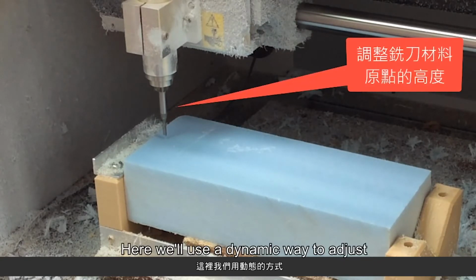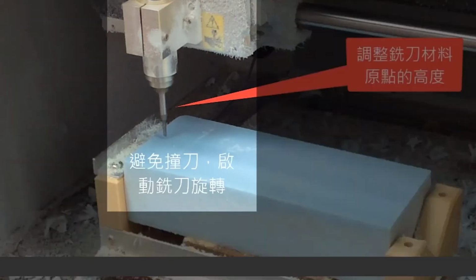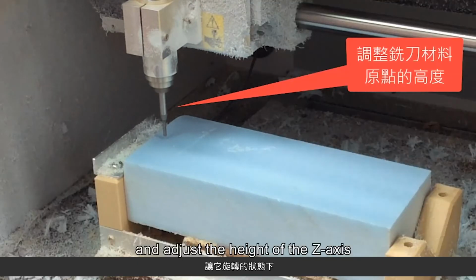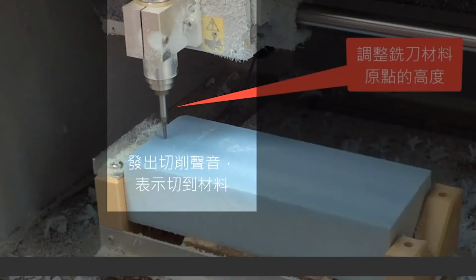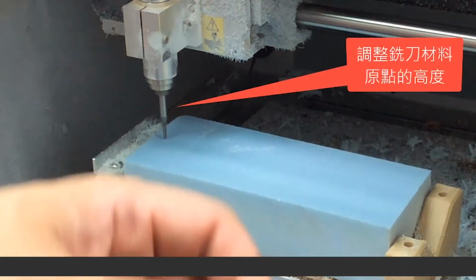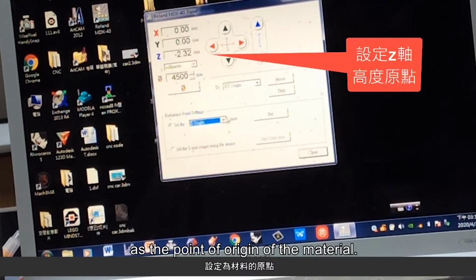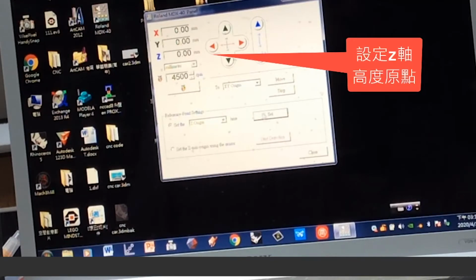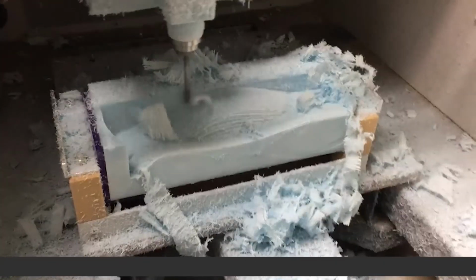Here we'll use a dynamic way to adjust the height of the cutter. In order to avoid hitting the cutter, we'll start the cutter axle and adjust the height of the z-axis while it is rotating. We'll set this height as the point of origin of the material. Next, we will start the CNC.